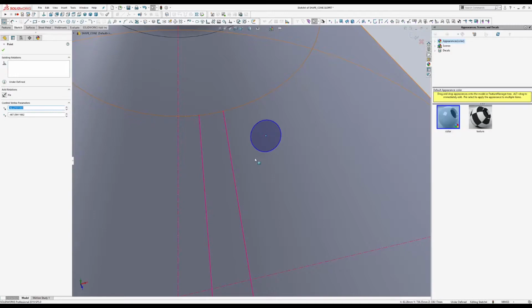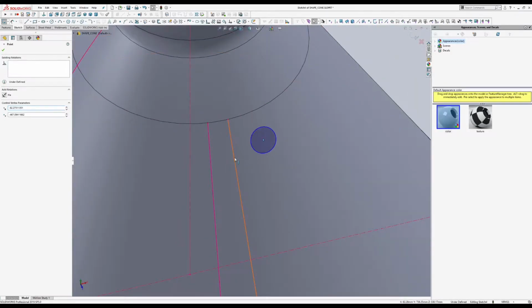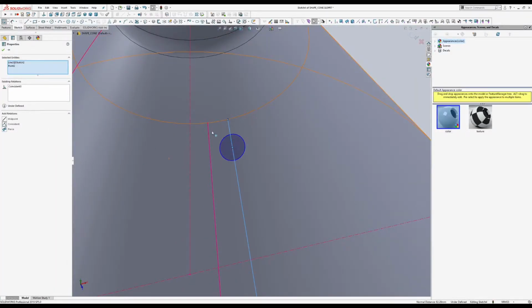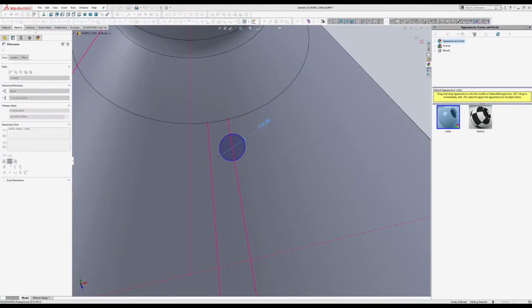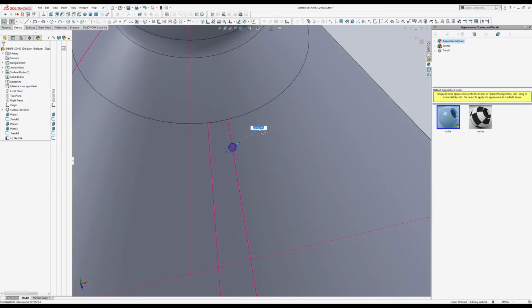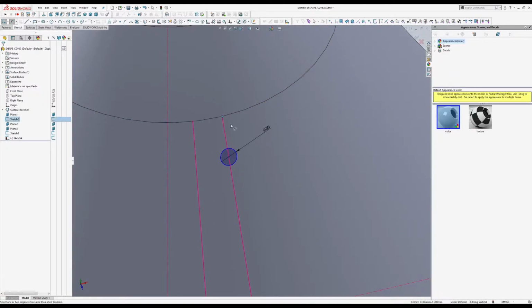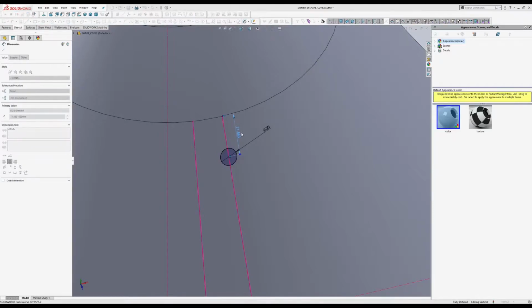You can draw it here, for example, and then you select the dot and this line, and you say coincident. You can make this 20 millimeters diameter, maybe a bit more, 30. Okay, so now in addition we want to make a dimension here, so let's say 50.